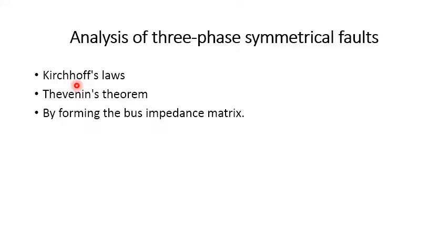Then draw the fault condition with the help of the reactance diagram. This is the same as the pre-fault reactance diagram, except that the fault is represented by a short circuit or by a specified fault impedance. Then we need to calculate the per unit values of the fault current in various parts of the system and at the fault point.